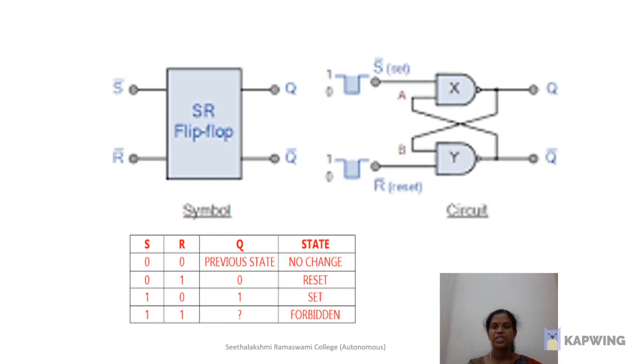SR flip-flop is a gated set reset flip-flop. The S and R inputs control the state of the flip-flop when the clock pulse goes from low to high. The flip-flop will not change until the clock pulse is on the rising edge. When both S and R are simultaneously high, it is uncertain whether the outputs will be high or low.